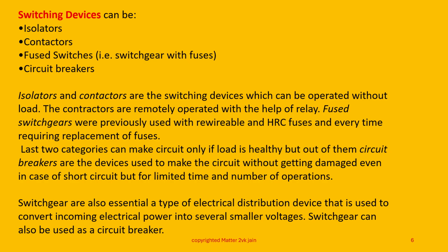And the contactors are remotely operated with the help of a relay. Fuse switchgear were previously used with rewirable and HRC fuse units, and which were every time requiring replacement of fuses in case when short circuit happens, they are blown.